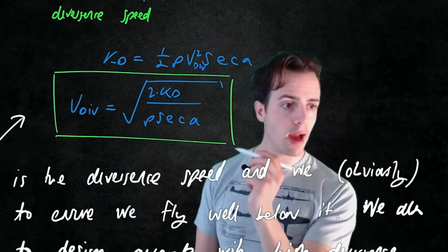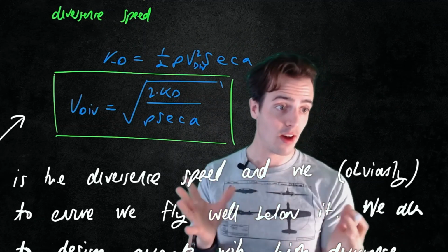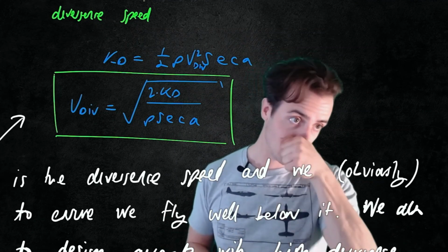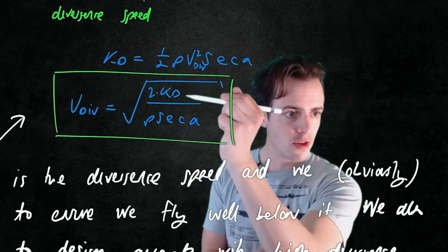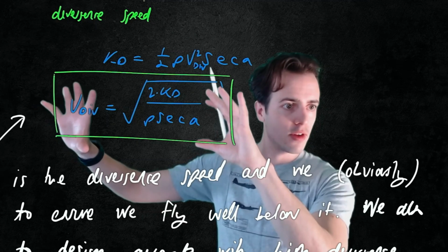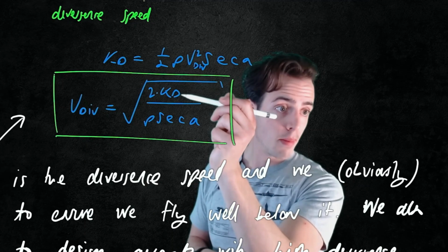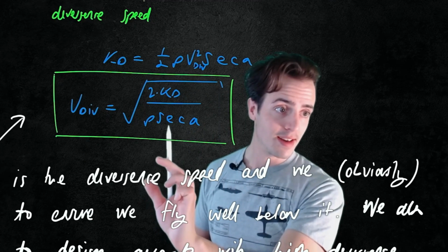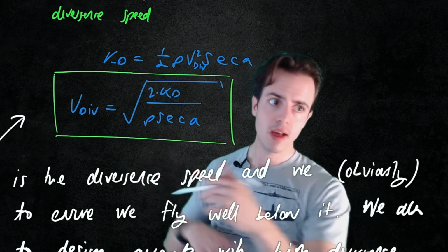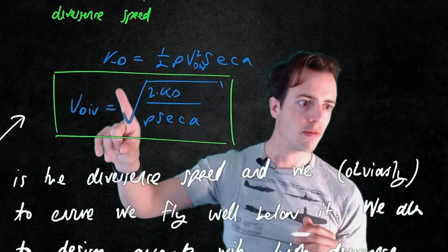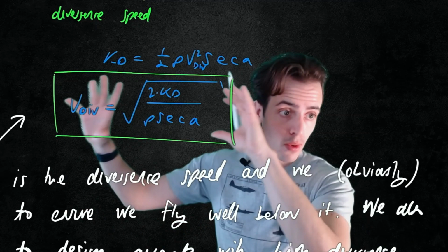Now, we spoke right back at the start of this course about the Fokker Dr.I and how it suffered from torsional divergence in the early test flights. Because of that, the designers were very keen to increase the stiffness of the wing. This equation wasn't understood at that point. They just thought we need to make the wing stiffer. They might have doubled this number here, but if by doing so they included another spar and made this number 3 times bigger, they would have reduced the divergent speed of the aircraft. So what the Dr.I example brings to light is the importance of this equation.